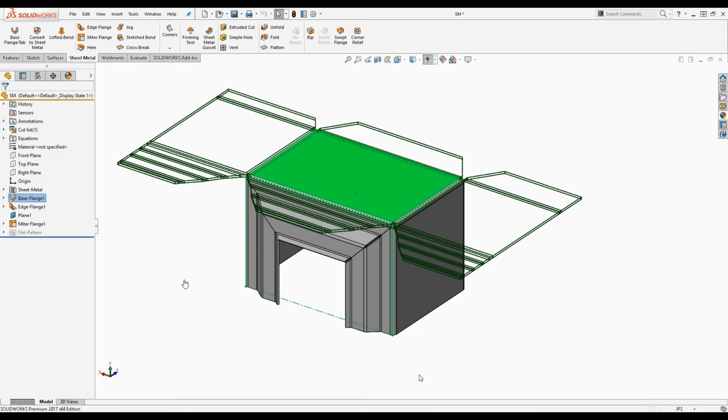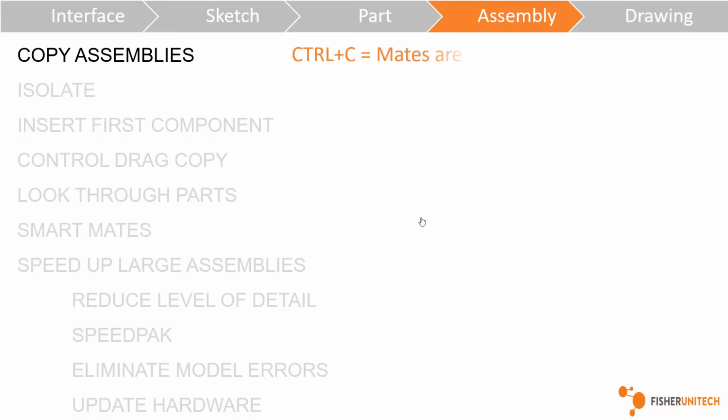If you get a preview, it means all your bends, whatever it is you're doing, are good, right? Previews are usually good. If nothing's showing, you know, hey, whatever feature I just did, I've got to go back and redo that, right? This is just a time saver, instead of going to flatten and clicking it again. It speeds things up and tells you whether any cuts or anything you were just doing destroyed it, right?